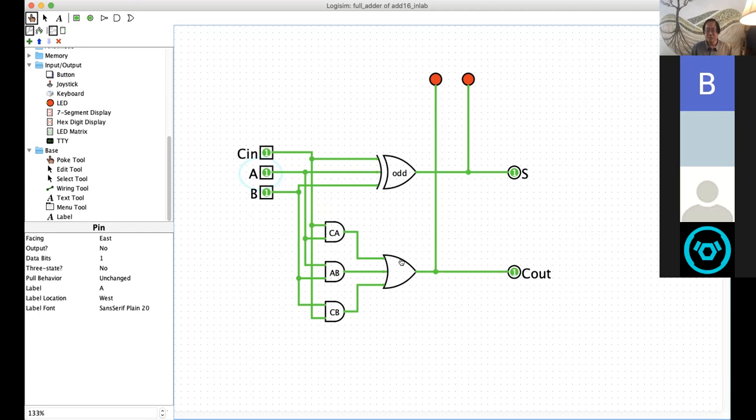We'll use this 1-bit adder, 1-bit meaning 1-bit position, in the scheme of things in the adder. Even though it has 3 bits of input, they're all the 2s, or all the 4s, all the 8s, whatever, right? So we're going to make a 4-bit adder, a 4-bit position adder out of this.